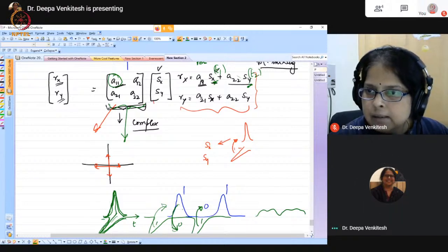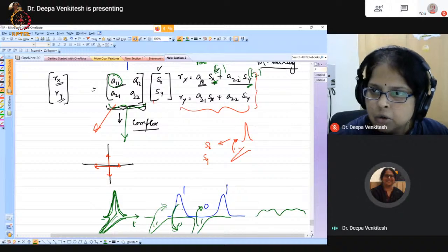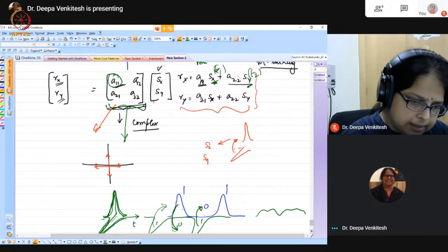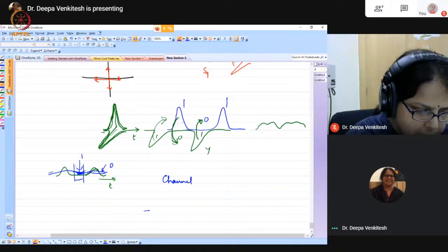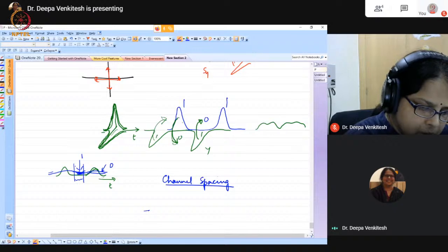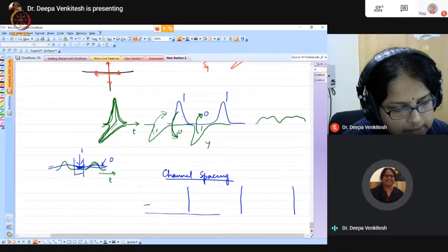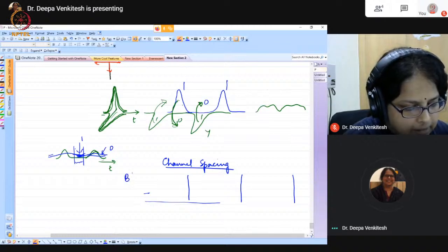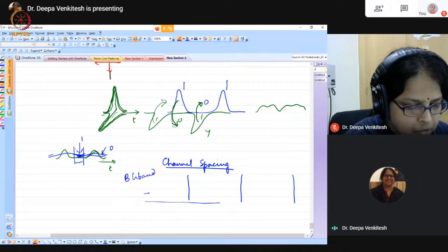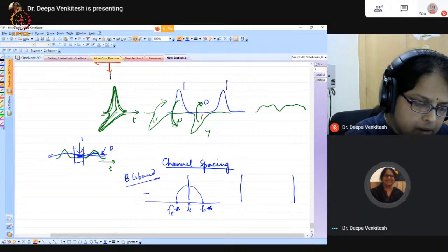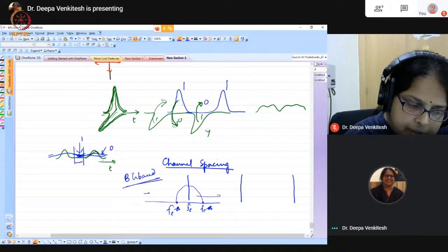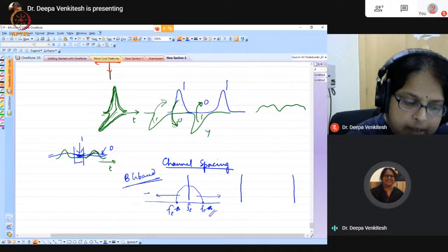There's a question from Shakti. What are the parameters that affect the channel spacing in communication? So I think you're talking about spacing in the WDM channels. If your channels are very widely spaced, you know that when you're trying to modulate at a specific baud rate, let's say B gigabaud, the first nulls will start appearing in an NRZ modulation at the carrier frequency plus B and FC minus B. If the channels are very widely spaced, you can possibly extend this, but how far you can extend is decided by how fast you can modulate.